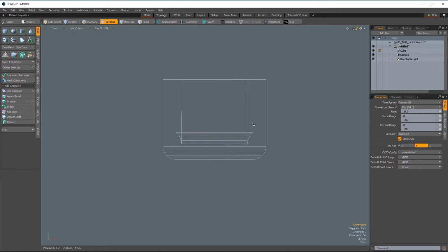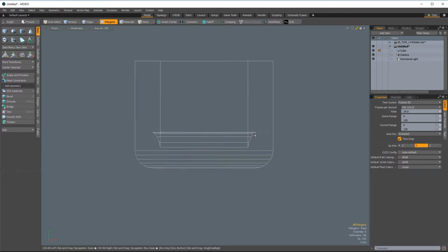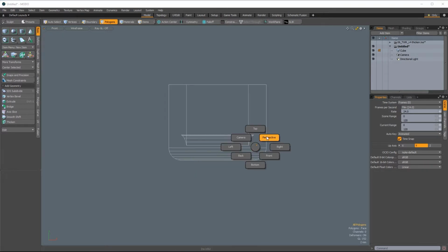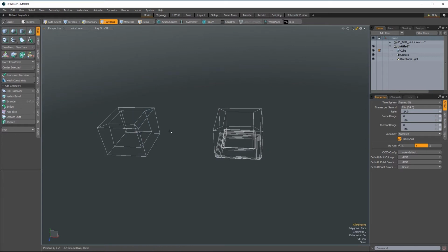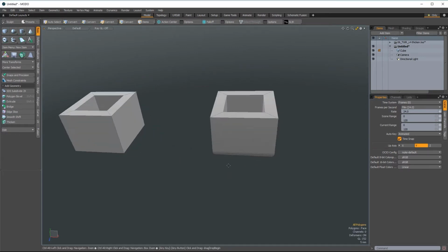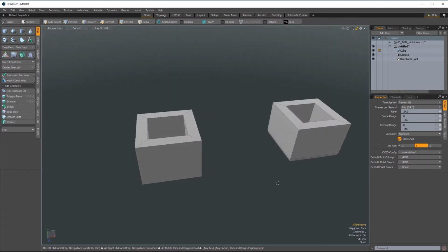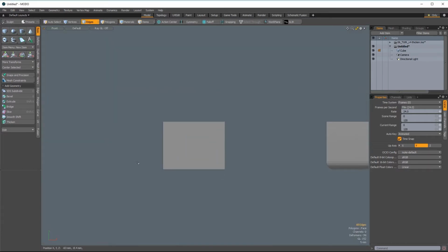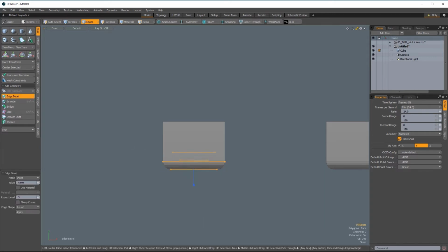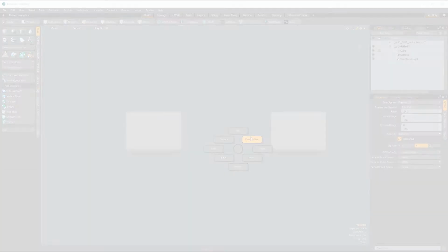It will be useless for exporting or using as a 3D printed object. So this is why I say keep your models as simple as possible for as long as possible. So in this case, it definitely would have been easier to save this filleting feature until after the thicken operation. And that would have worked a lot better.